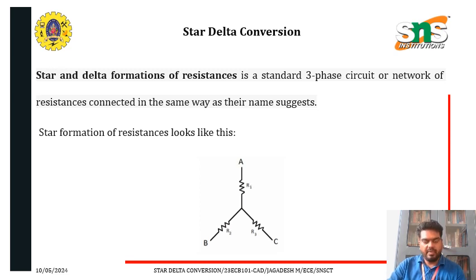Here in our first unit or the second unit, we used to find the equivalent resistance by means of the series and parallel method. If two resistances, named R1 and R2, are in series, we add them, so R1 plus R2. If they are in parallel, we use the formula R1 R2 by R1 plus R2. This is the method we use to find the R equivalent value.